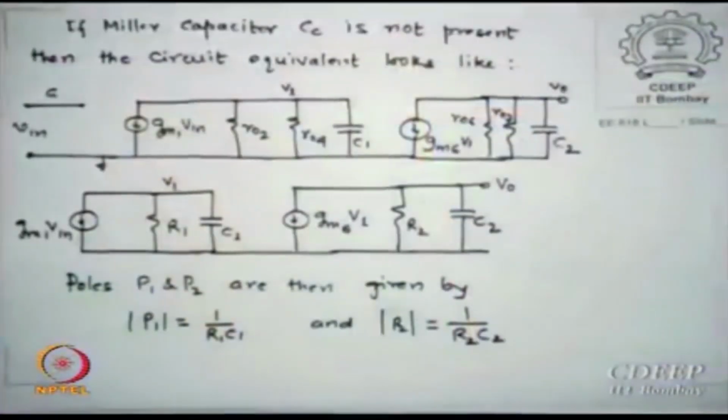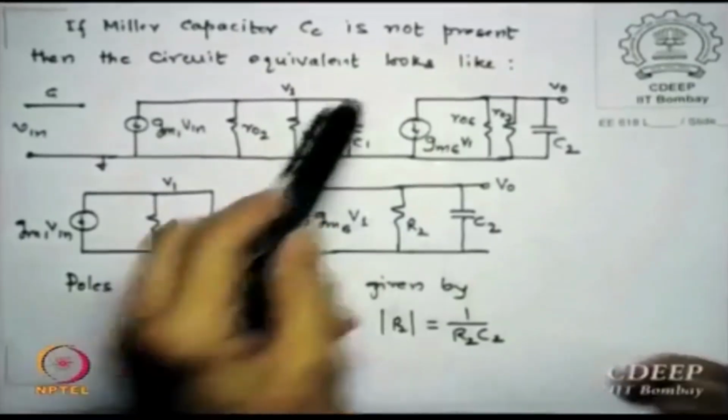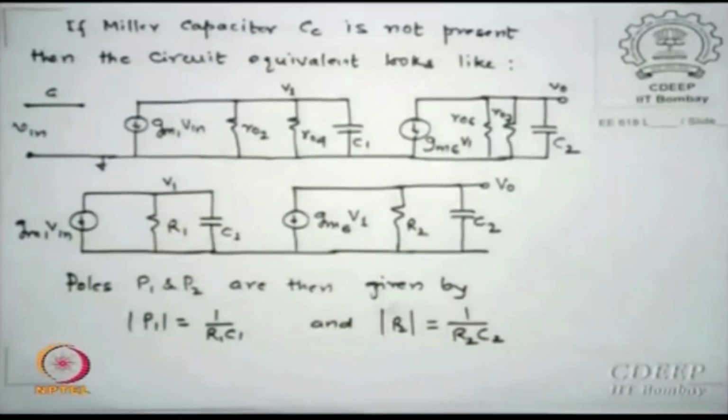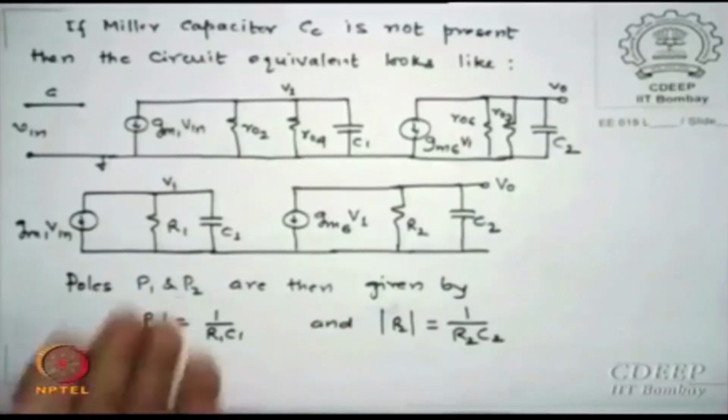Okay. Now before we quit this area, before we start OPAMP design, there is an issue. This was all done with CC available. I should have done the other way, isn't it? Without CC, so let us do without CC. If I remove CC, I can see my input poles and outputs without any calculus, zero time constant technique.